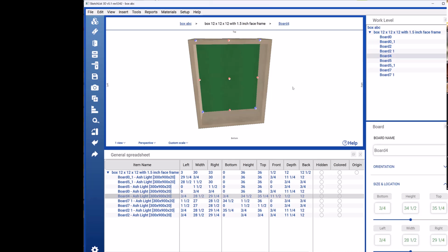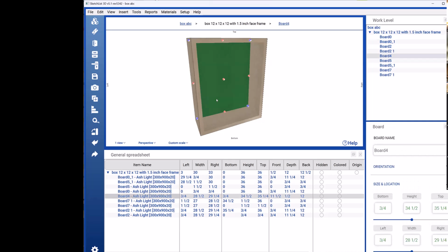The work that you put in up front matters, because I don't want to have to second guess when I get down to the shop whether I actually stretched that to the 1/4 inch over. If I cut that one 42-inch wide by 75-inch tall piece of Luan that I'm putting on the back, or that piece of 1/4 inch on the back, and it wasn't sized correctly, because I just stretched it to the edge like Dave shows in all these sessions, because all he does is use the shift key and he stretches to the edge, but he didn't stretch it the extra 1/4 inch to make it the right size. And so I always got to think about, okay, let me go in and check where's the left side of that, or I go into